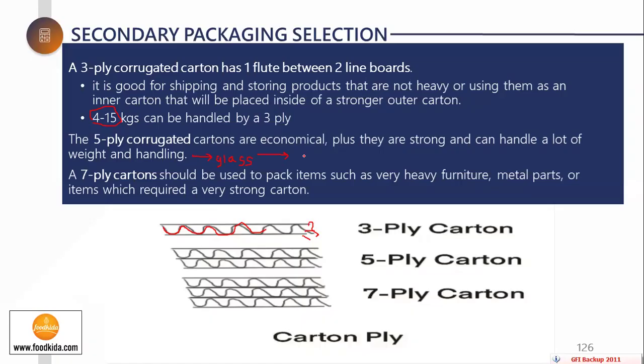Does it have any lamination? No, it's a simple PET bottle with a sticker on it, and I fill 12 bottles of 500 ml in one carton. So 12 kg is the net weight. Add the weight of the bottles, maybe 30 to 40, whatever it is, 200 grams. So 12.2 kg. But I can still work with a 150 kg compression strength. Why? Because of the strength of the PET. This is the PET bottle I'm talking about.